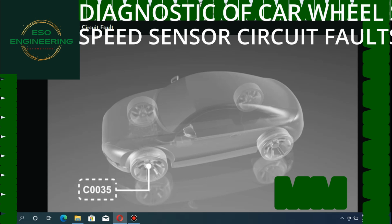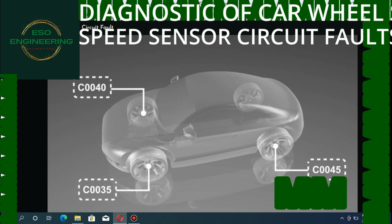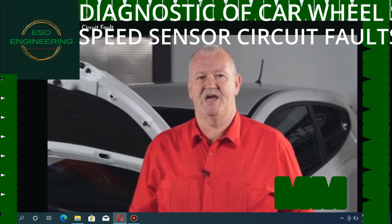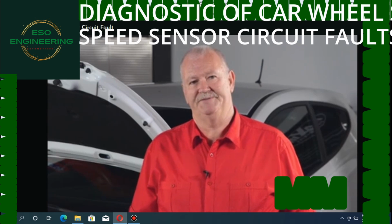C0035 is for the left front wheel speed sensor, C0040 for the right front, C0045 for the left rear, and C0050 for the right rear. The diagnosis of these sensors is the same, only the wires to the ABS module will be different.